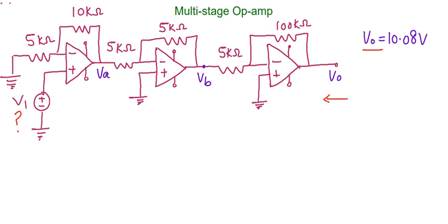For the last op-amp, the positive terminal is connected to ground and we have the supply, that is VB, at the negative terminal. So this example is of an inverting amplifier. As in the previous case, the positive is connected to ground and at the negative we have the voltage supply. Again the amplifier is an inverting amplifier. And for the first amplifier, since the supply is given at the positive point, it is an example of a non-inverting amplifier.